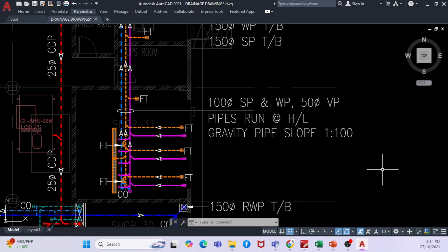Okay, that is the above, this is the below. So you can see that there is a WC, the pipes from the WC. What is the header? This is the header, 100 soil pipe. Even though my standard says 75, I will follow the local code, which is 100.